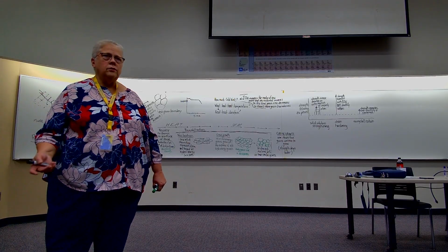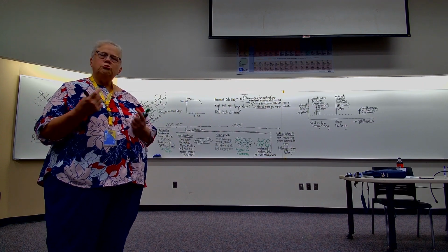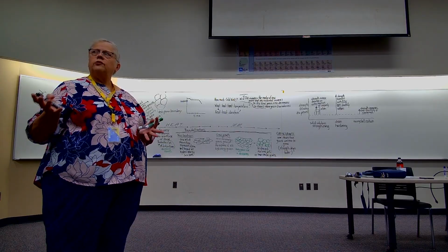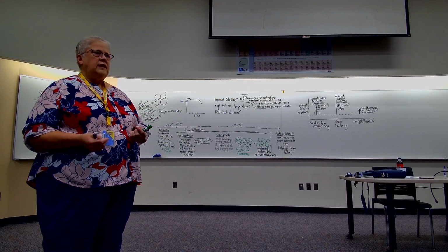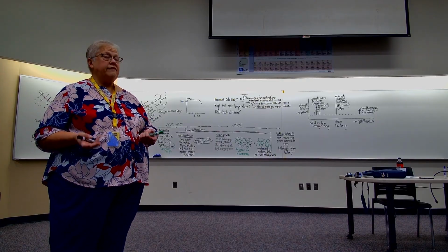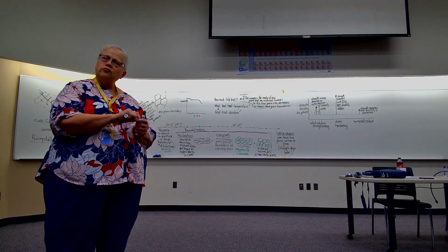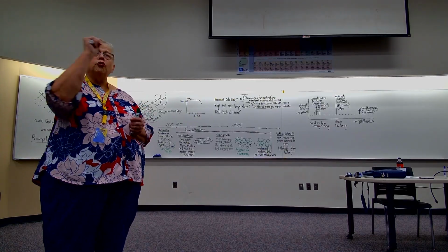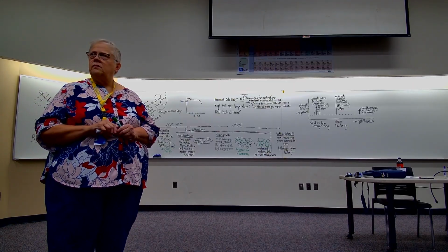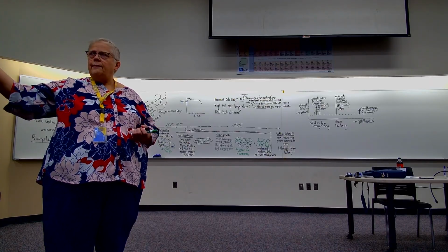There are metals that are actually, within the metal, 2 different solids. They're distributed in different ways. They each have a different composition and a different crystal structure. And the way that we distribute one into the other, the harder one into the softer one, determines the strength. The biggest example is steel.